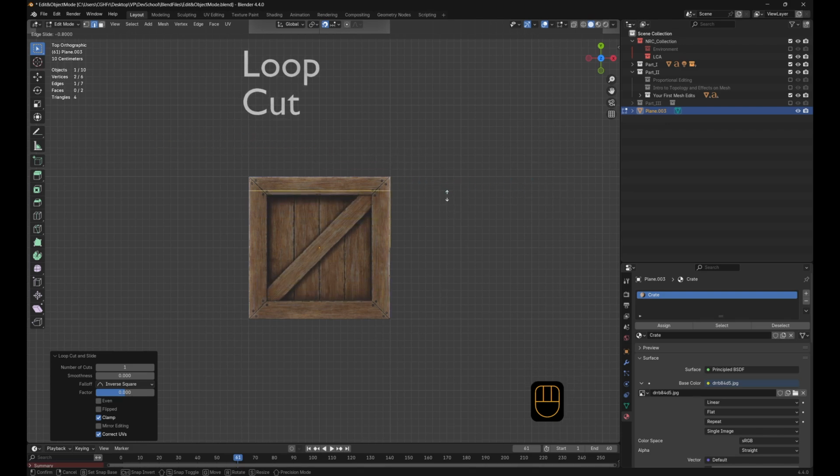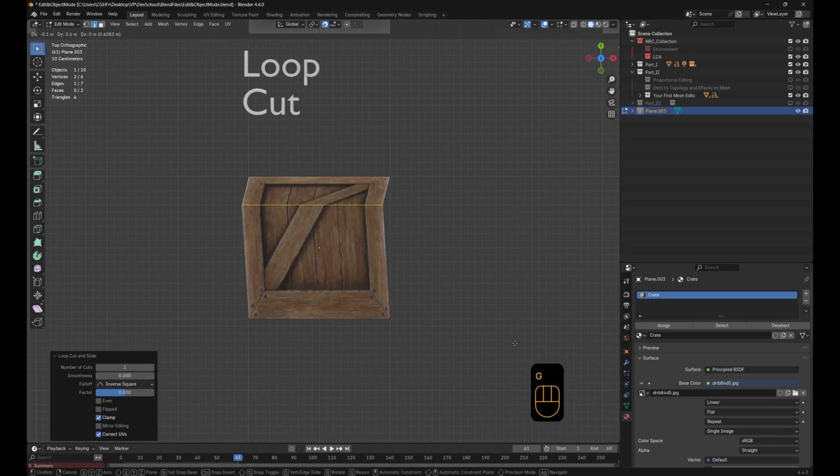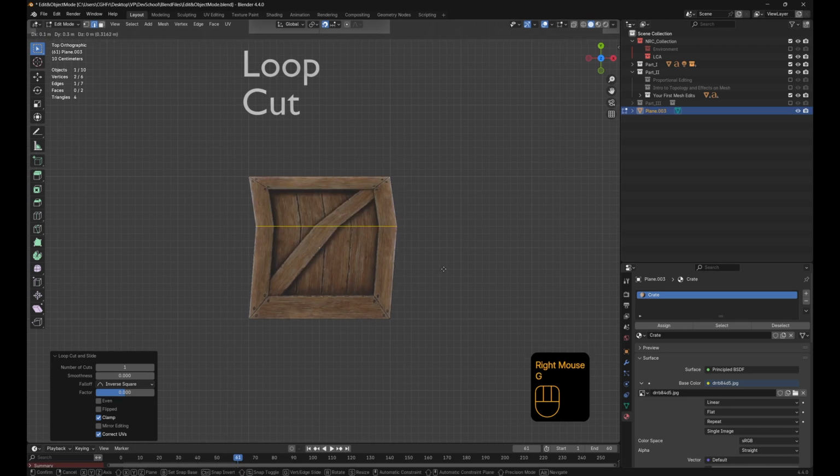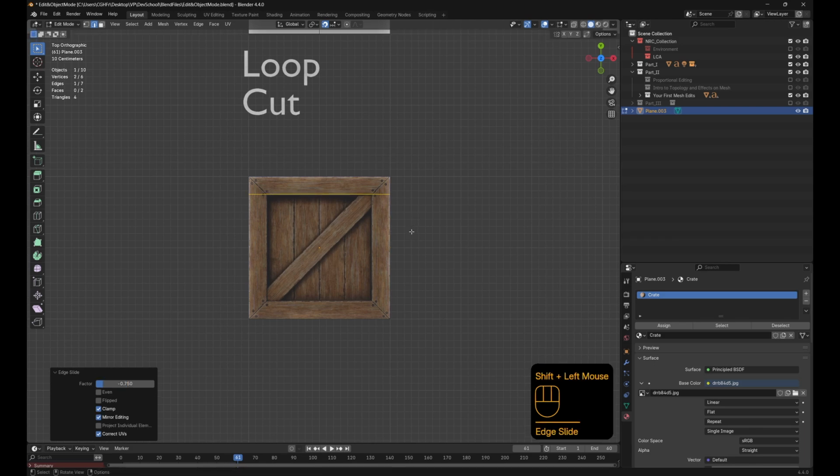without affecting the texture. And then if I hold Shift, because I have snapping turned on with increment, I'll leave it on for now. You can see if I press G to slide, you'll see it's snapping to the grid. You can see it's snapping to these grid squares just here. Okay, and then when I get up here, it just goes either side. It's not very good. So what I need to do is just finesse this by holding Shift. And I can do smaller increments and get it right in the right place. There we go.